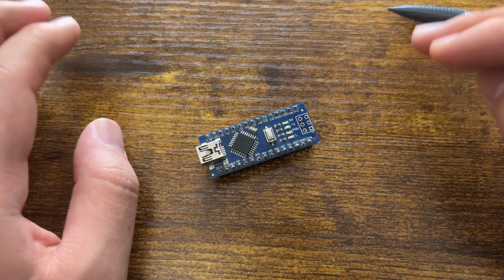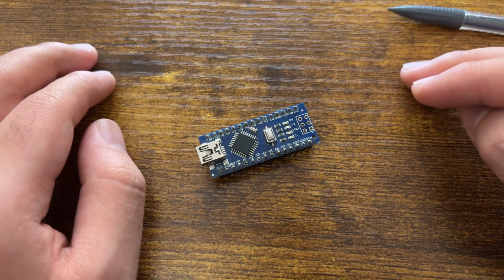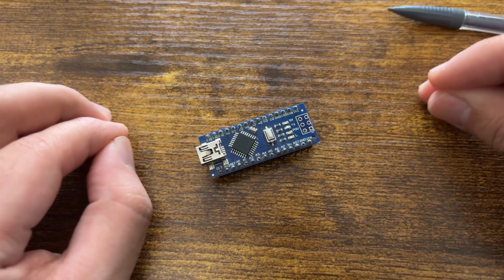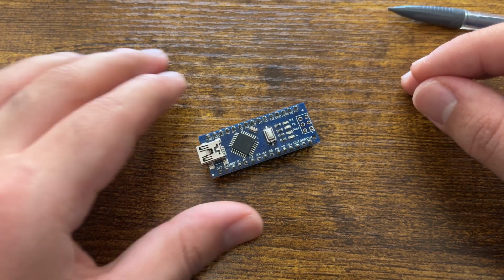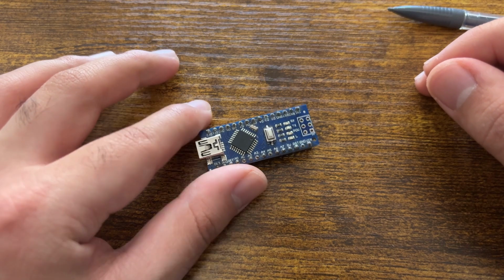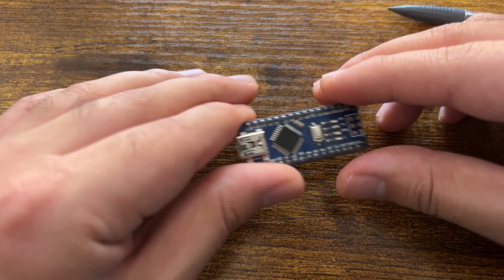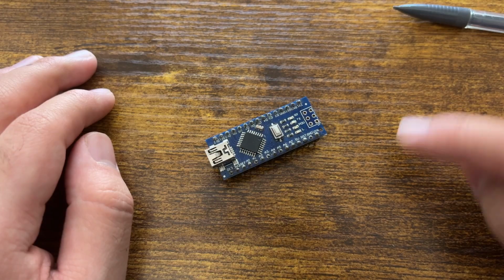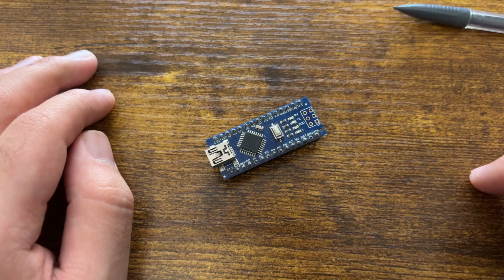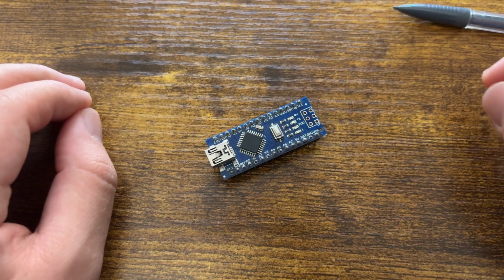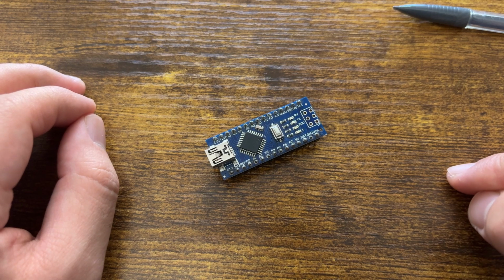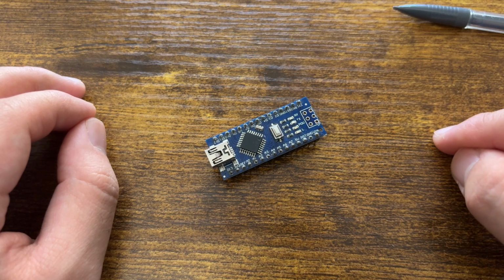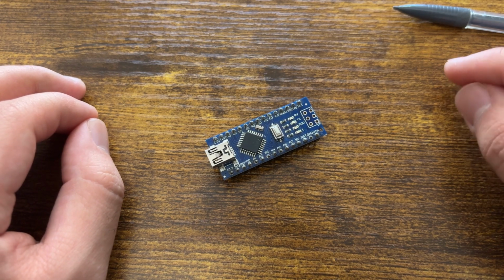And again, what it means to understand the USB language, the USB protocol, is just to tell this microcontroller what these zeros and ones mean. And probably, as you know, microcontrollers and any computational machine, computer, microcontroller, they speak zeros and ones. But these zeros and ones we can interpret in many ways. So for example, these zeros and ones can be in pulses, but we don't know what each pulse means. For example, if it's going from 0 volts to, let's say, 5 volts, or 3.3 volts, or even 12 volts. Some of the protocols use 12 volts.